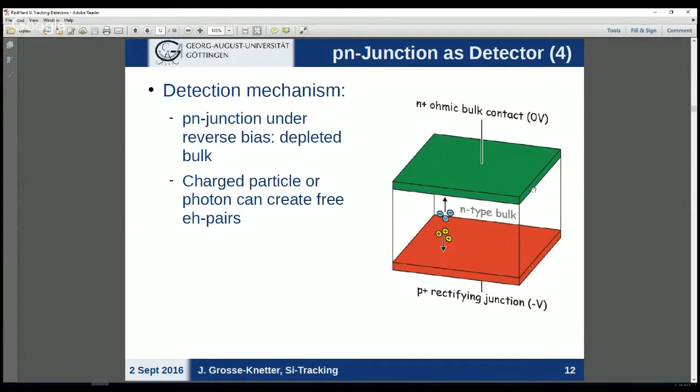So in other words, what would our detector now look like? We have the substrate, so that's more or less a chunk cut out of a silicon wafer. This non-colored part is the lightly doped bulk. Then at the bottom, in that case, we have the p-type highly doped part added. So at the edge of both, we would have a p-n junction. We apply an external voltage, extract all the intrinsically existing charge carriers so that the entire bulk is free of